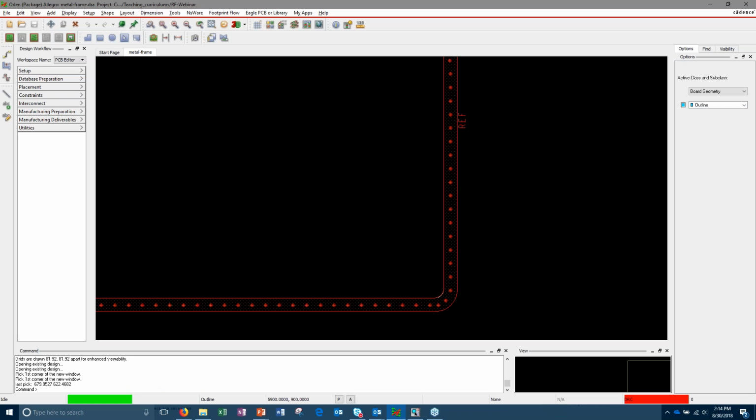So at this point here, I want to show how we could get some of those components. In this case here, you're looking at a fence that I'm creating. And the reason I create the fence as a logic symbol instead of a mechanical, even though it's a mechanical part, is I want to go ahead and get my ground vias in there. And I can go ahead and open that up, create this symbol, make it electrical. That way I can go ahead and tie my RF ground to this frame that I'm going to set down. And then you can see my vias already placed in there that will be connected to the plate there.